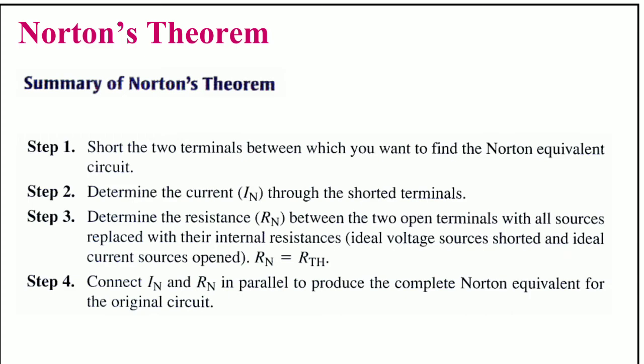Step 3, determine the resistance Rn between the two open terminals with all sources replaced with their internal resistance.